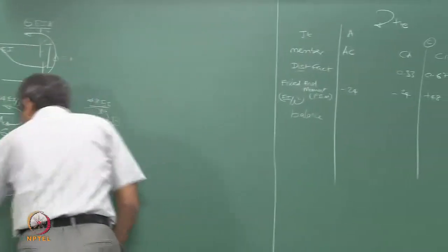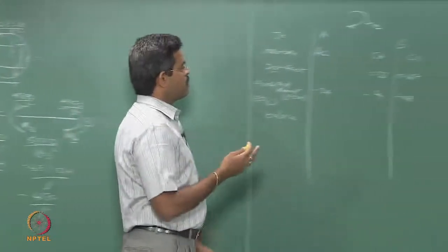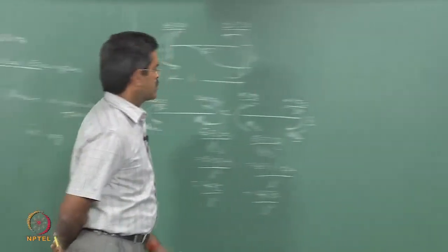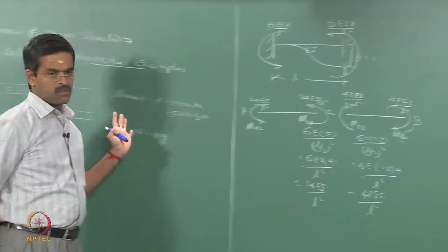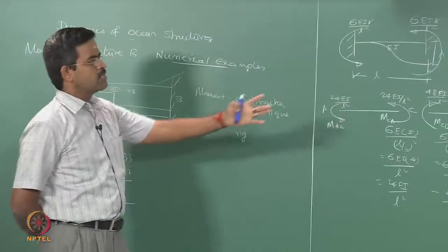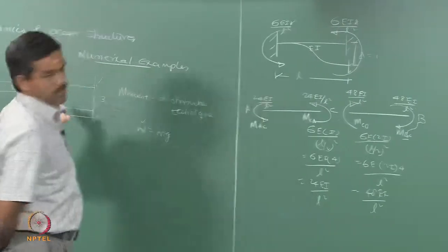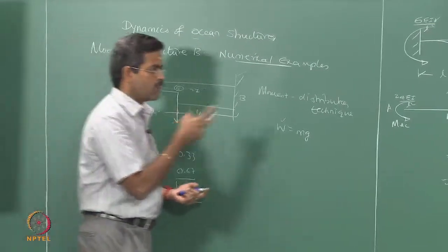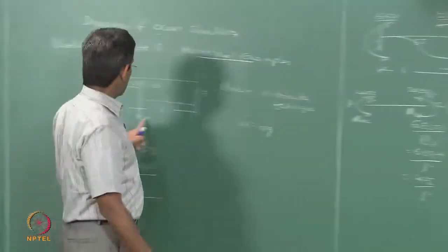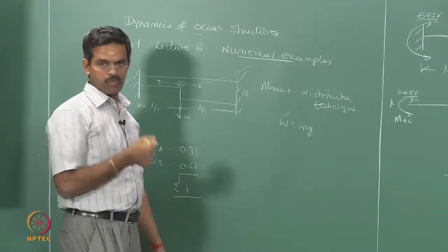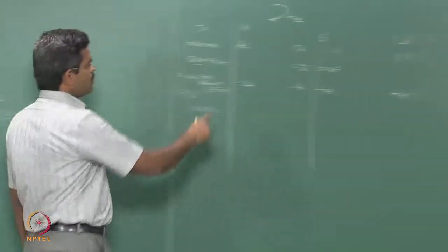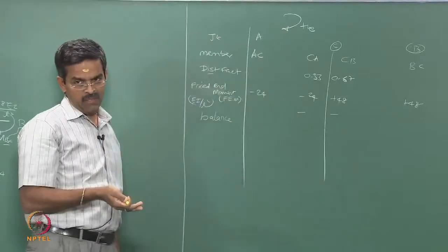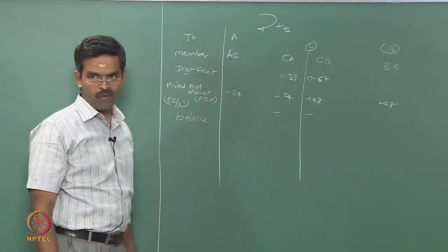Now, how do we balance this? It is very easy, you must know the procedure, but anyway for people who do not know this, let us quickly explain. Appreciate that we are trying to follow the principle of structural mechanics applied onto dynamics to find out K equivalence. We are not interested in finding the BMD, SFD for this problem, no. We are interested to know the natural frequency of the system, it is vibrating, that is very important. So, I want to know the equivalent stiffness K, so I am using delta equal to 1 here. I am trying to get the force responsible for this. Now the positive number is higher, therefore the balance will be negative. Positive number is higher, therefore the balance is negative all the time.